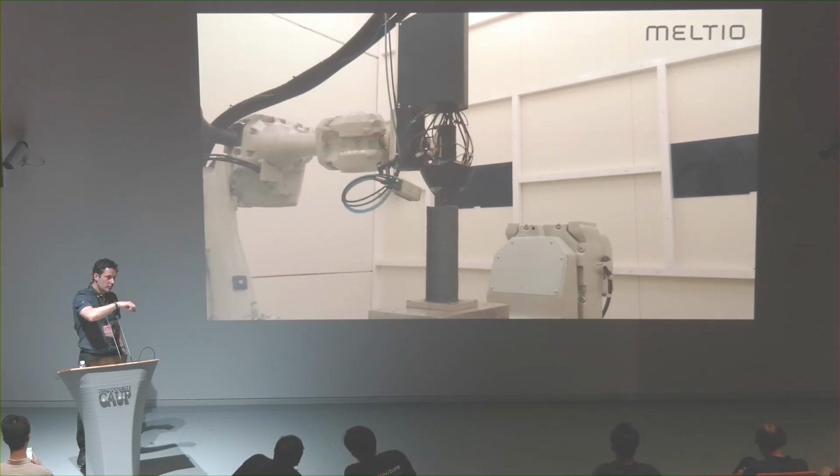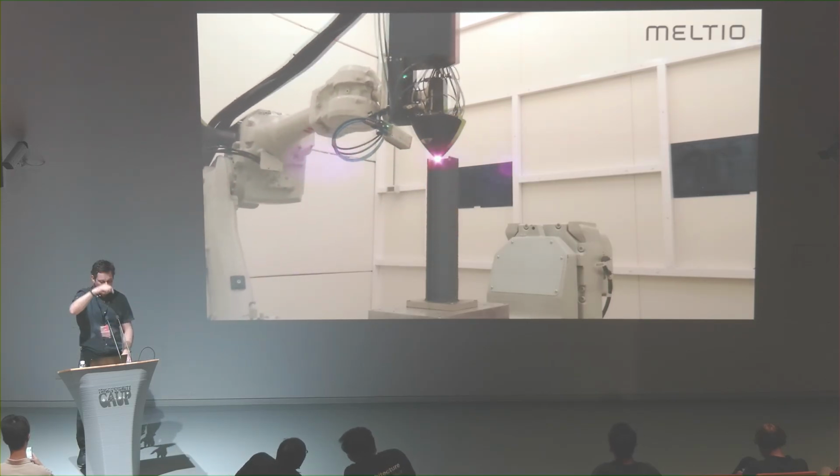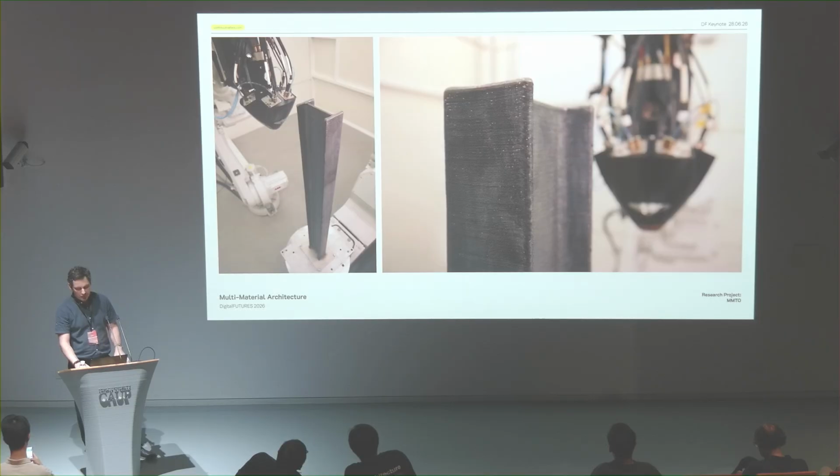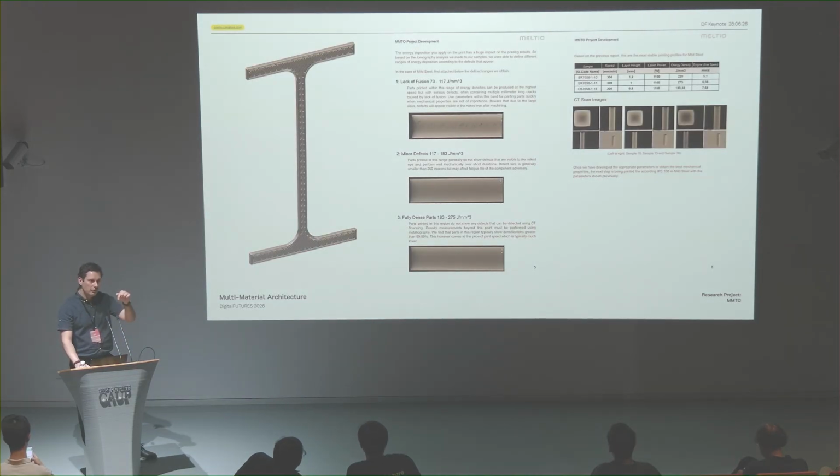I mean, this is quite a simple extrusion, like you just do it upwards. And this is the result. Something quite interesting here is the more energy they use, the more the metal coagulates. So you can see the difference here at the top in the middle. It has these little black spots, and this is where the metal hasn't stuck together properly.